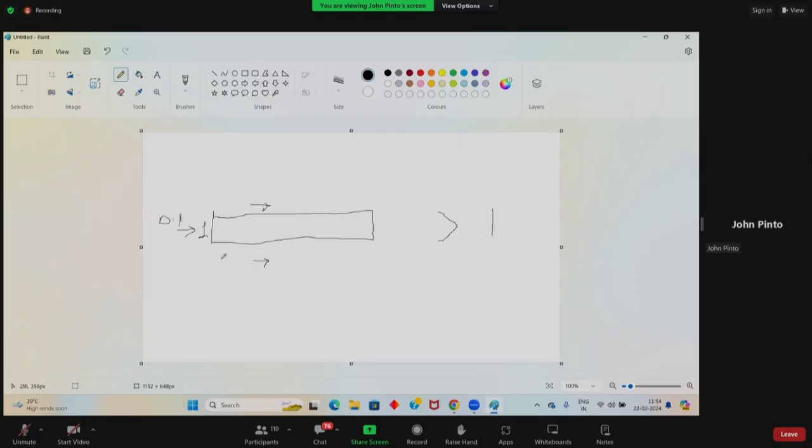My domain length is 1 meter. Now, can you tell me at the outlet, when can I expect the tracer to reach? I've injected the tracer at the inlet with a velocity of 0.1 meter per second. For it to travel 1 meter, it will need, as he said, 10 seconds. So if I monitor my scalar concentration at the outlet, I should see my scalar reach there at 10 seconds.